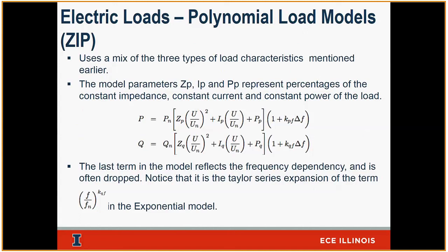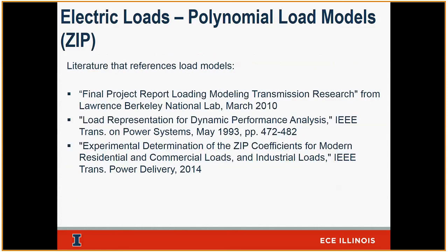detailed models can help you understand and analyze that, just like this one here. This is the polynomial load model, and it has a Z component, an I component, and a P component. These specifically describe the behavior of every load that you might have. And this could be an experimental type of exercise. There was a paper, and I think I've referenced it somewhere here. This one: experimental determination of the ZIP coefficients for modern residential, commercial...